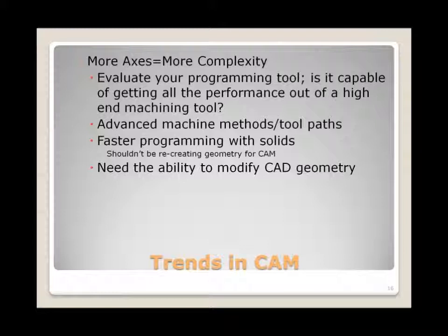And especially when you're going to be introducing advanced machining methods, TCP, and being able to control your process better, advanced tool paths, and as John said, just having a stable process instead of just a high speed process that requires your operator to be there watching the process and speeding it up and slowing it down. So what we're able to do with our software is control the process and have the feed optimized based on the chip load and based on how much it's cutting, so it makes for a more stable process.